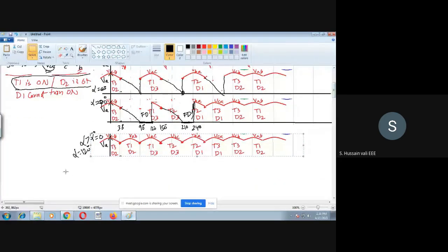So alpha is equal to 120. Just see yourself, this is 30, so from 30 to 120 it means 150. So here you will find out the delay till 150. If you find out the delay till 150, you simply erase all these parts. In this case, what you find out is that this black color waveform will become 0 here, and after that it will become 0.